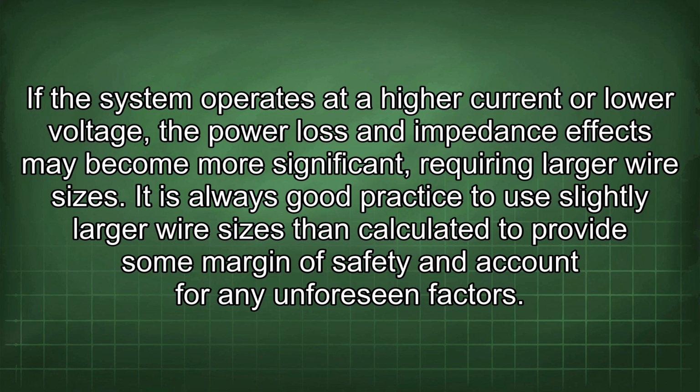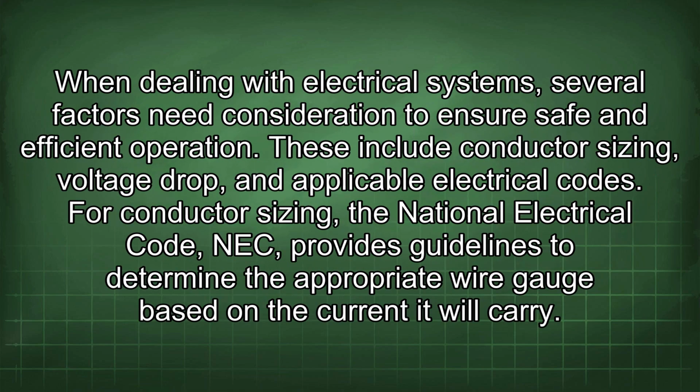It is always good practice to use slightly larger wire sizes than calculated to provide some margin of safety and account for any unforeseen factors. When dealing with electrical systems, several factors need consideration to ensure safe and efficient operation. These include conductor sizing, voltage drop, and applicable electrical codes.